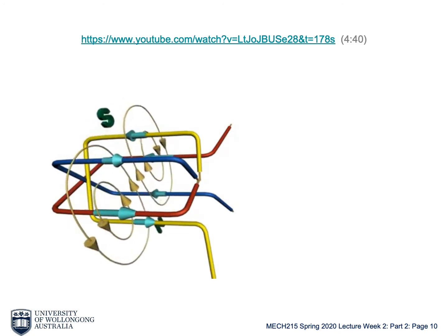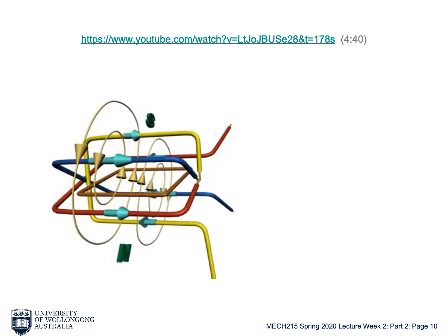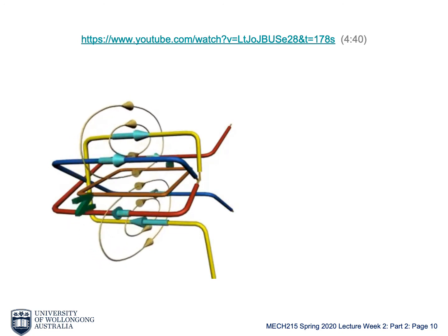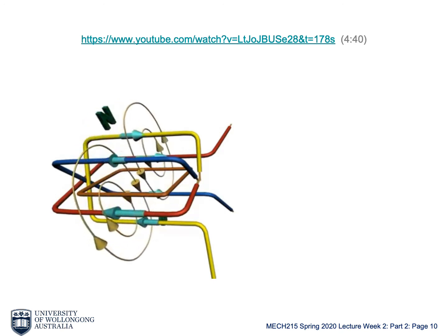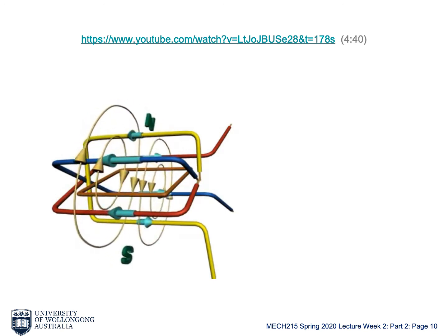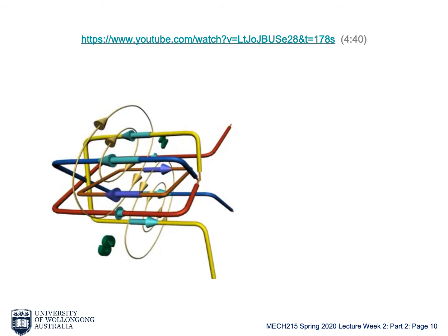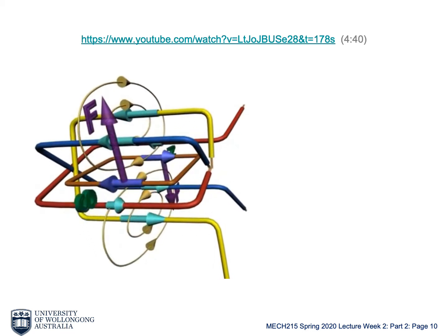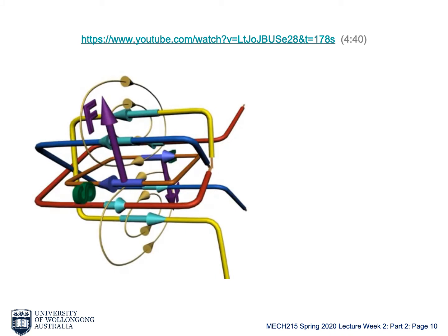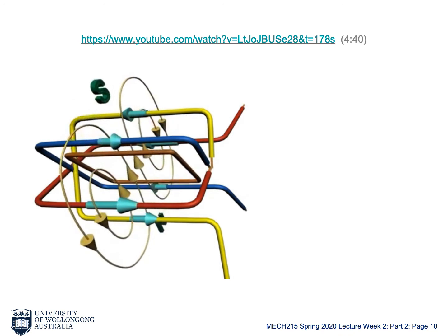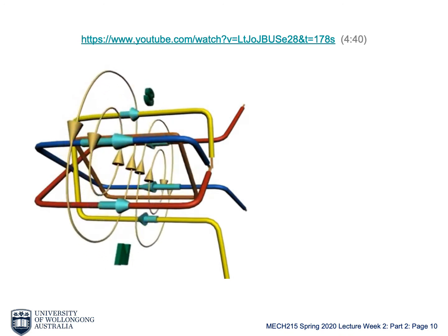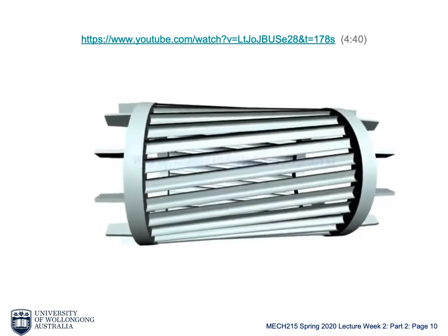Assume you're putting a closed conductor inside it. Since the magnetic field is fluctuating, an EMF will be induced in the loop according to Faraday's law. The EMF will produce a current through the loop. So, the situation has become like a current-carrying loop situated in a magnetic field. This will produce magnetic force in the loop, according to Lorentz law. So, the loop will start rotating. A similar phenomenon happens inside an induction motor also.